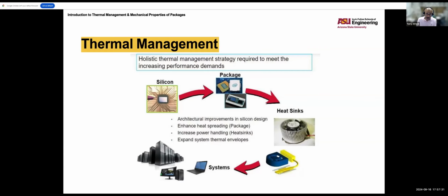So the heat is not going to go through the ceramic substrate. It has to go back up through the covering. And that was an aluminum can that had a half-inch chill water line coming to it. So you can imagine how much heat was being generated if you needed a half-inch chill water line just for that one package to remove it.